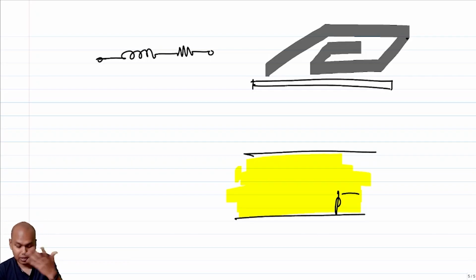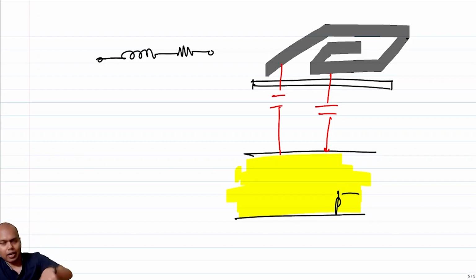It has basically mobile holes associated with it, and the top metal layer is not at outer space, right? It is sitting on the same chip, which means it has a close proximity to the substrate, which essentially means I can expect some distributed capacitance associated with the entire metal line that is on the top and the substrate.